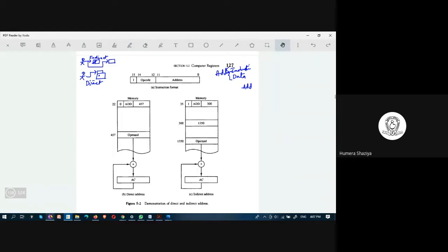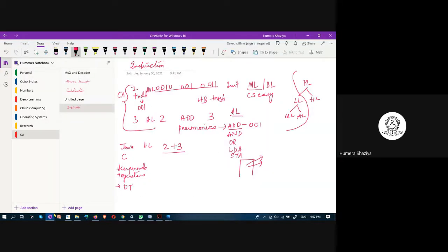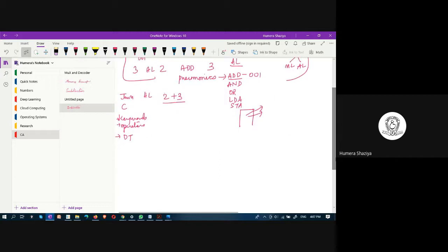For that, you need to understand this. The instruction now has split into three parts. Our instruction has an address part. How many bits long? 12 bits. Then opcode, how many bits long? Actually, you learned that opcode was 4 bits, but opcode is 3 bits now. Why is opcode 3 bits? Because you are introducing a mode bit. This is known as the mode bit.